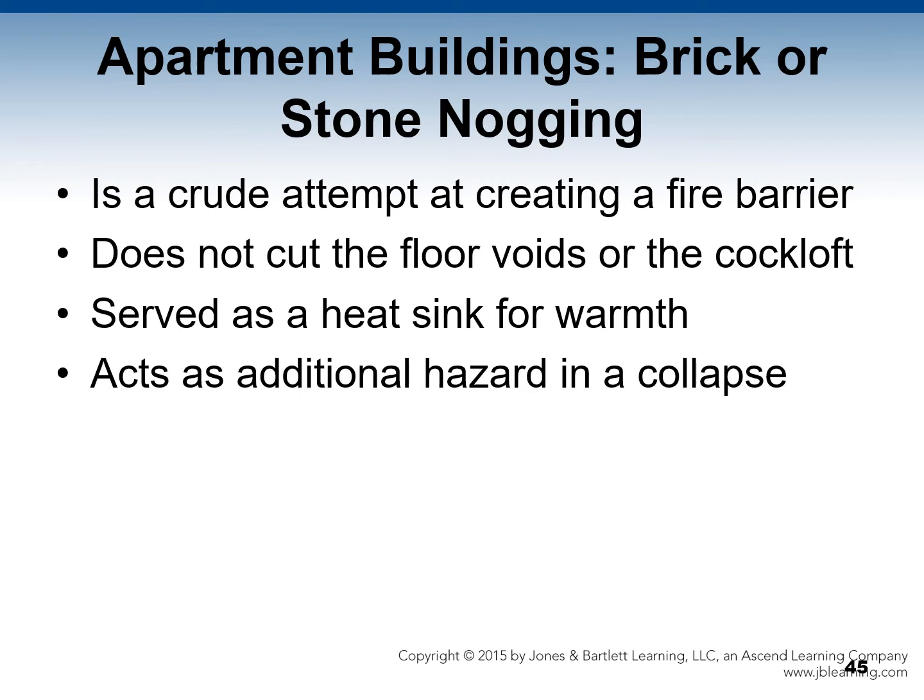And that's partially why it was constructed. But this presents an additional hazard in collapse. So not only do you have the normal things that are common to collapse, but brick nogging can let go and drop a heap of bricks from between these stud beams.